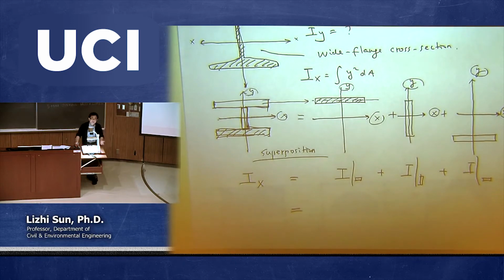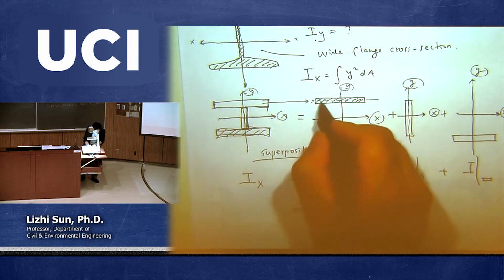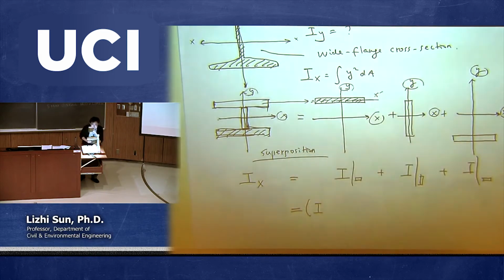So through that theorem, we can in fact calculate this one. Originally this is the moment of inertia with respect to the centroid axis, you call it x prime for example, and then plus A d squared. So all we need to do is to identify these two terms and add them together, which is the first part.